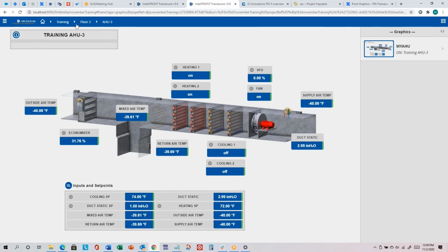I've heard of other people dividing the airflow input by the max airflow set point and using that as a percentage to drive the damper. So you can do damper animations for a VAV. I just didn't, because unless you buy our VAV controller that has a special actuator with feedback, we don't know the exact position.